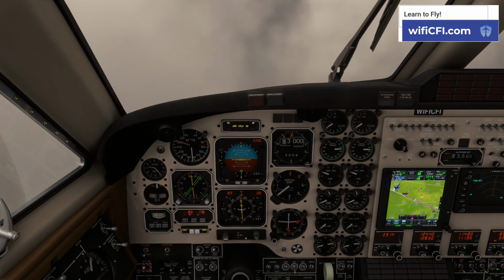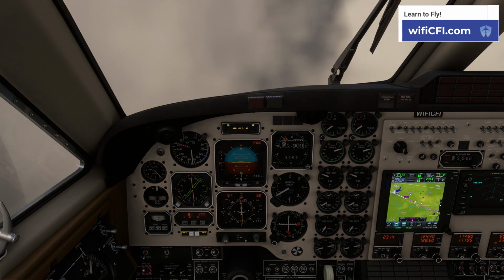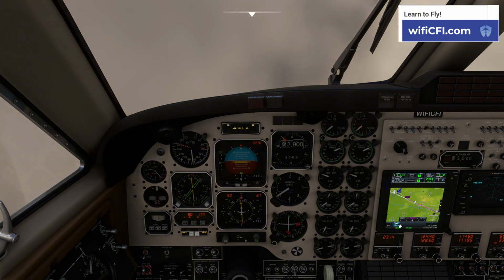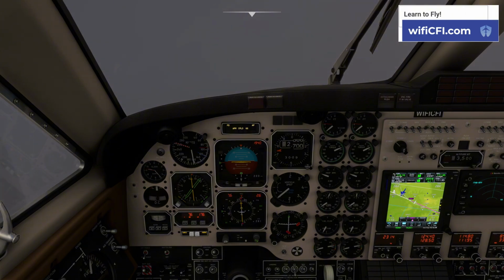Flaps are to approach. Airspeed's looking a little fast, so we'll bring some power back. Obviously that throws off the whole deal. Glide slope looks good. Localizer looks good. After panning, since we're going straight in, we're going to go to 673. We'll call it 700 feet.